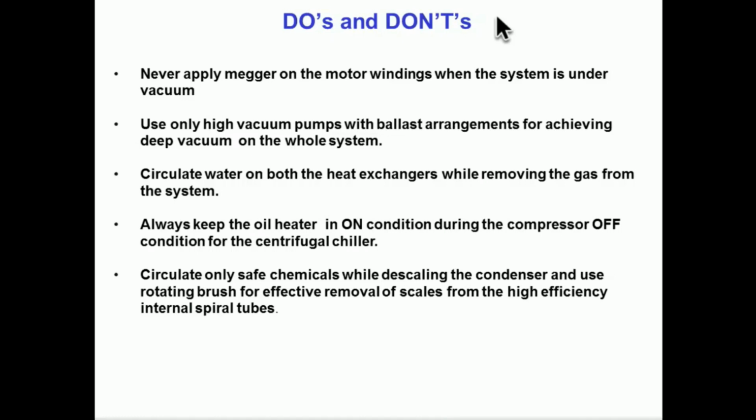To remove scaling, always use a rotating brush with chemicals for high efficiency internal spiral tubes. Modern compressors and condensers are all internally spiral and externally finned to improve efficiency. But unfortunately, within 3 to 6 months, many times we have seen them completely fouled.